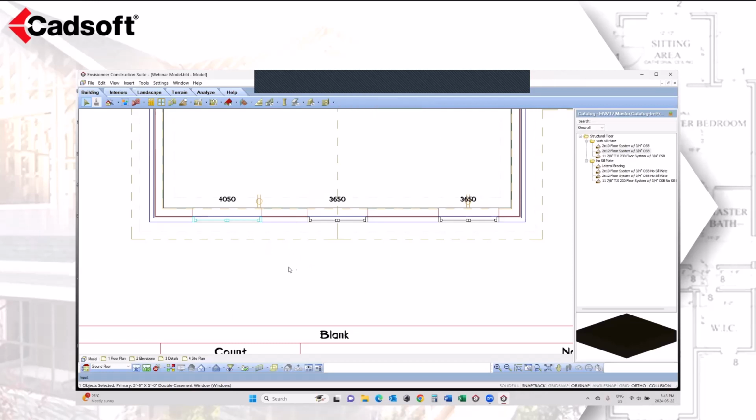With the windows and the doors, I'm going to select this window. Now that it's placed in there and I've changed it, I want to automatically center it on the wall. Before, centering on wall was only there when you were placing it initially in the wall. But now you can come through once it's in, so you can quickly place them and then go back and say, center that on the wall. Okay, so that'll give you flexibility.